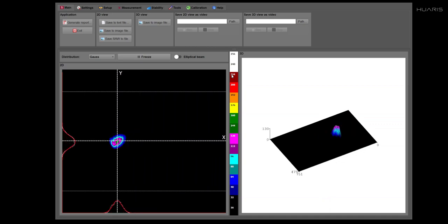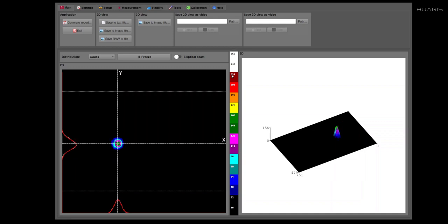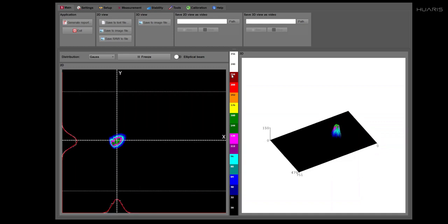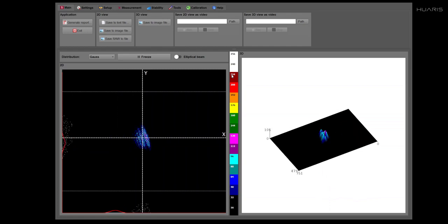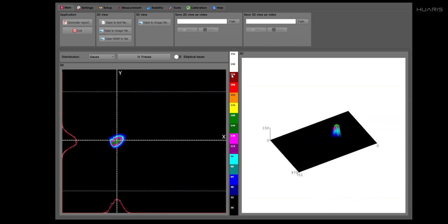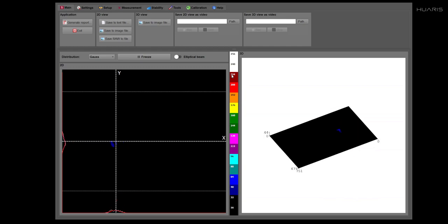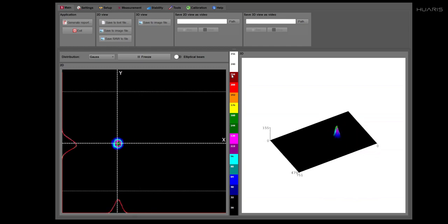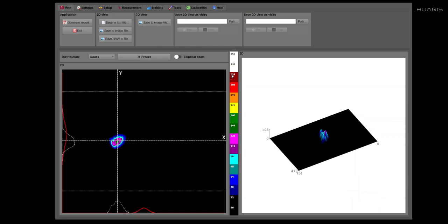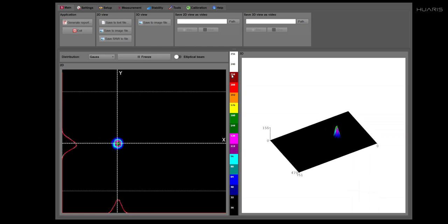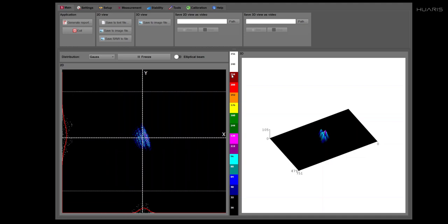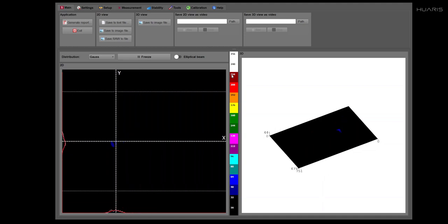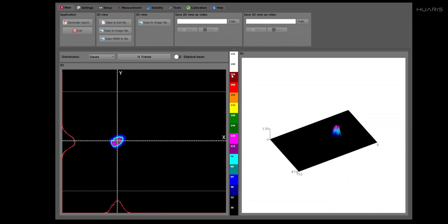The X and Y axis define the planes where we do section of the beam, and the measurement points or real data from these sections are shown in the bottom and on the left hand side of the 2D view as white spots, and these spots are then interpolated with an analytical function.